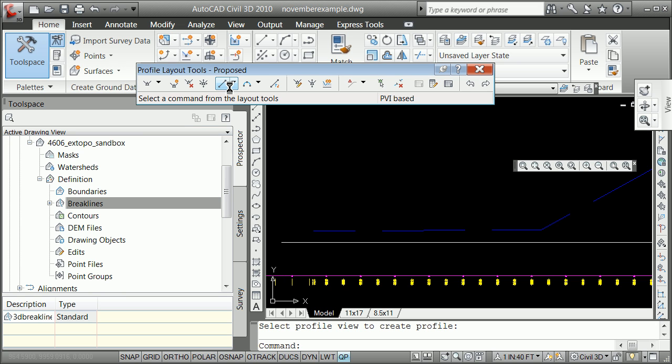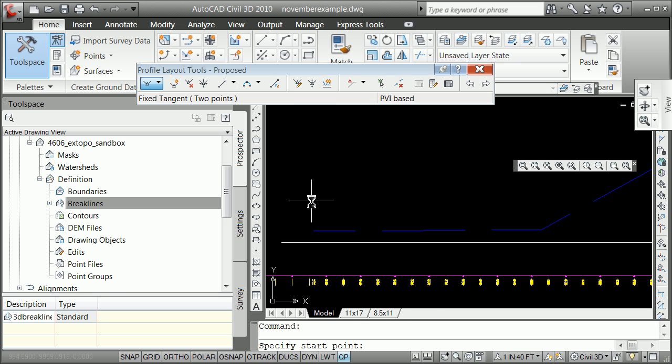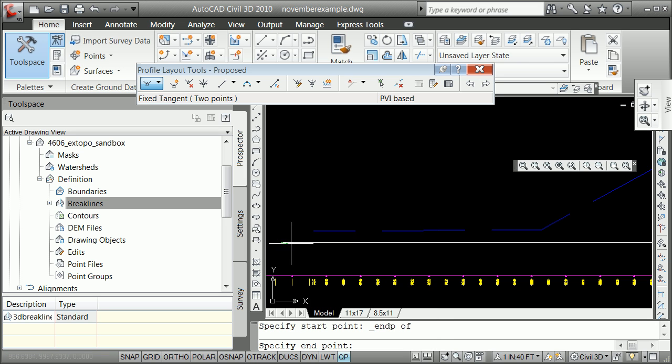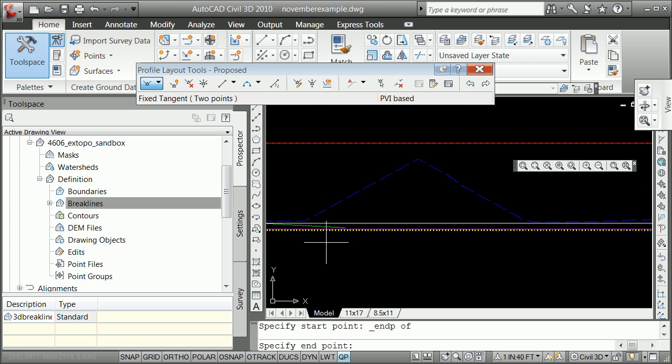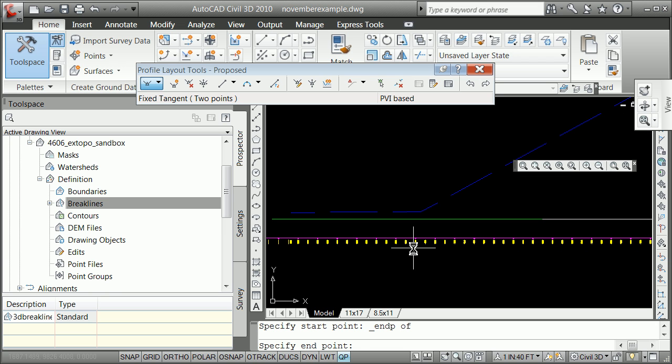And so we're going to learn to do this all by fixed tangent 2 points, starting point, shift right click from the end point there. You're drafting over the top of what you did before. At that point, if you're smart, you could do your, you notice it's trying to grab here, you could do your at 200 comma minus 4, which becomes minus 40.